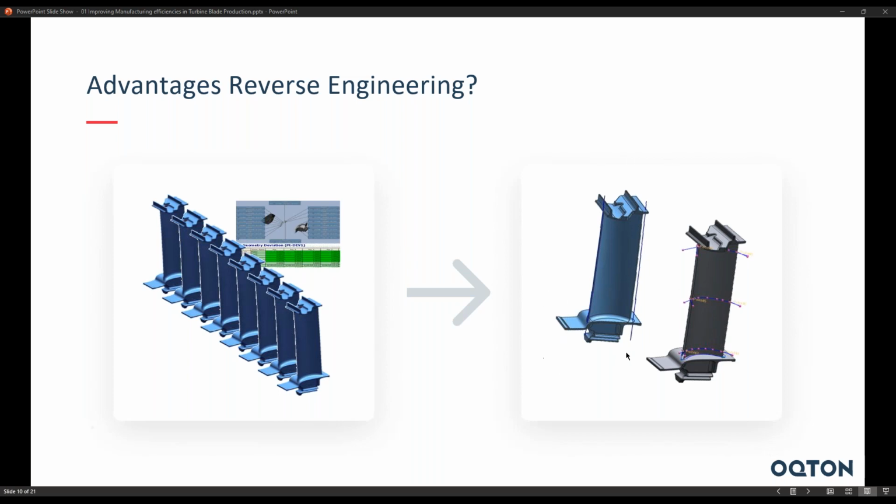So you have a better way to cover yourself in averaging out some of those tolerances and errors and defects in the shape of the part, and thus getting you closer to that original design intent to then make these parts anew, right? So, this is a major advantage of 3D scanning, is that ability to average many, many parts together. And I'll show a brief example of that in the live demonstration portion of this presentation.